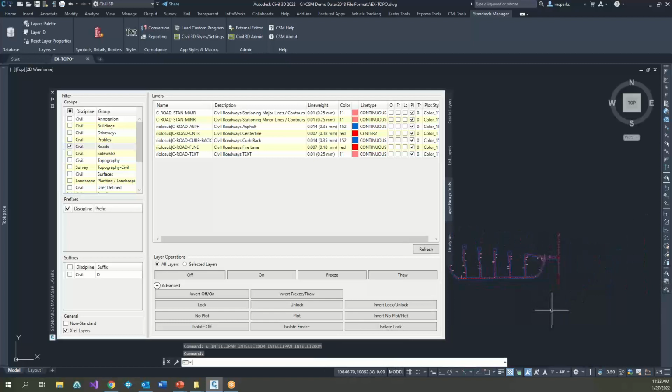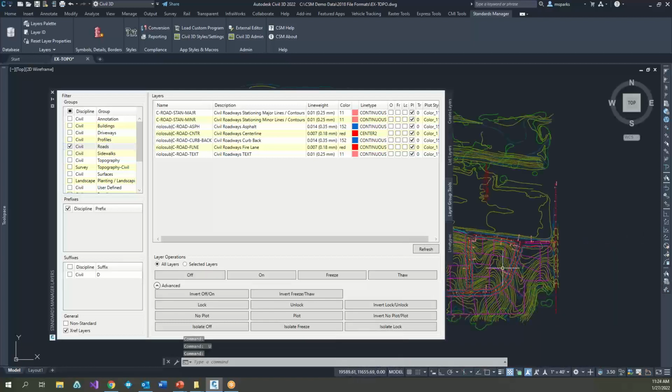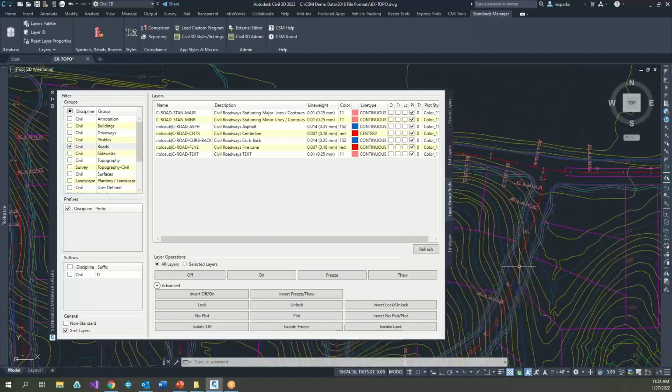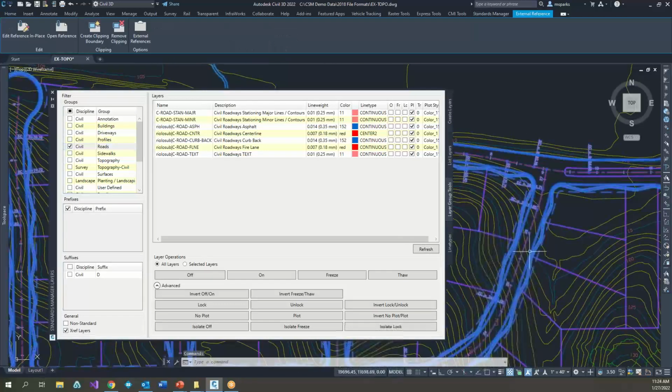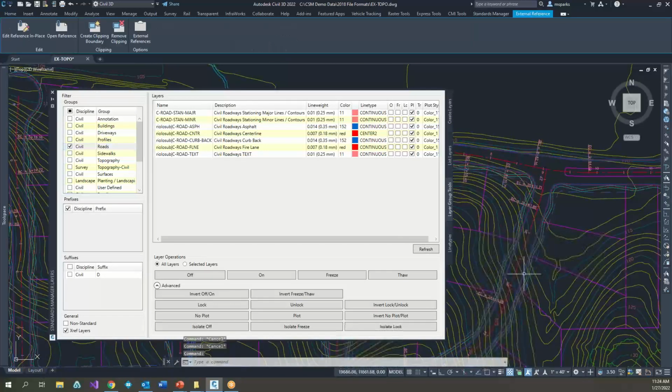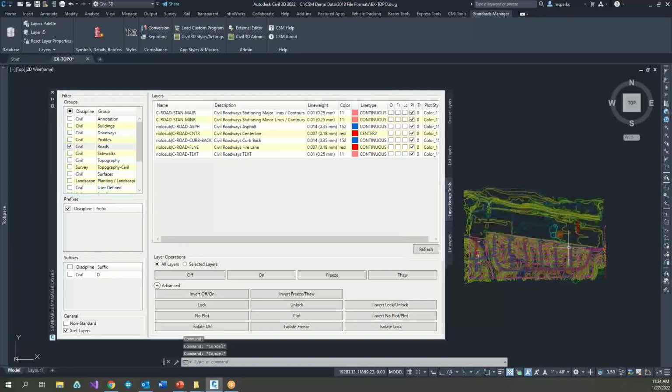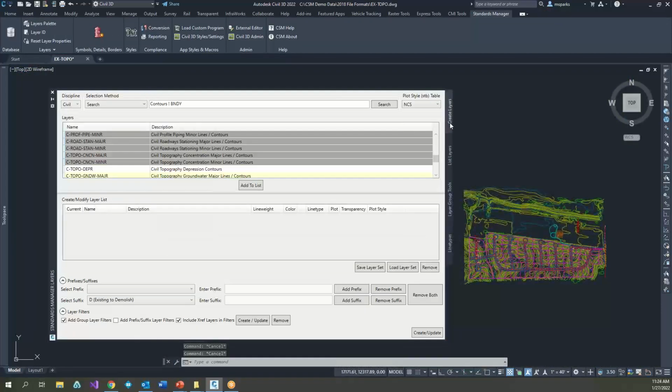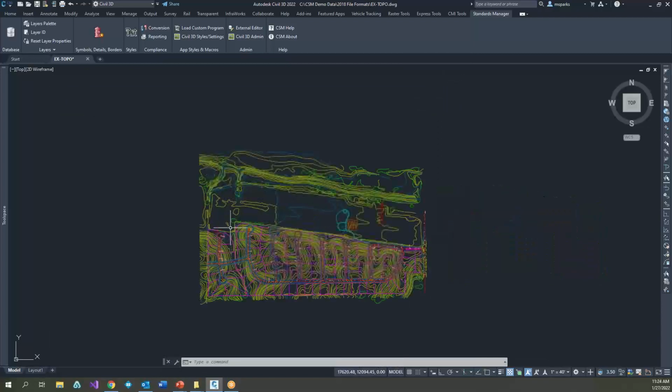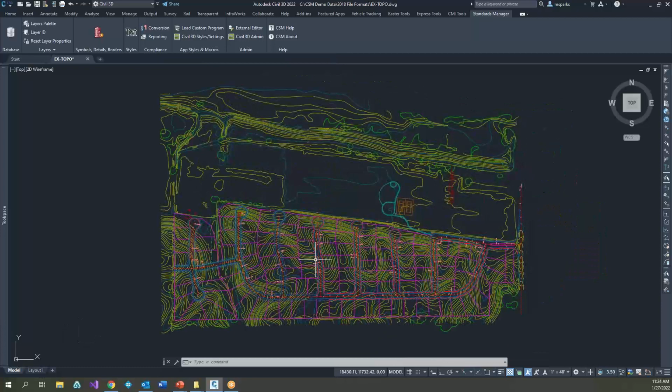Okay. Of course, I can get back. I'm just undoing. So there's a quick way to isolate certain groups on how you want to actually view them. Instead of doing layer isolate, you can do this. Now keep in mind, it was isolating through that X reference, because there's a layer isolate command. You can't really pick through an X reference. So that's kind of a nice little tool. So a lot of different little things you can do with layers to get things standard, to start standard, etc. That way we can start using the standard stuff versus having to go about and fix it all later. So it's a little easier to get the content in there while we go. Okay.